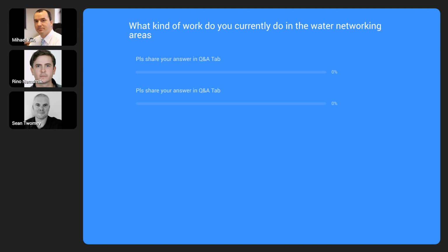So we are just sending the input data as an INP file to the EPANET engine. EPANET is calculating in the background and sending the data back to your familiar BricsCAD environment for visual analysis through data tables, through thematic maps, through the profiles, and so on.